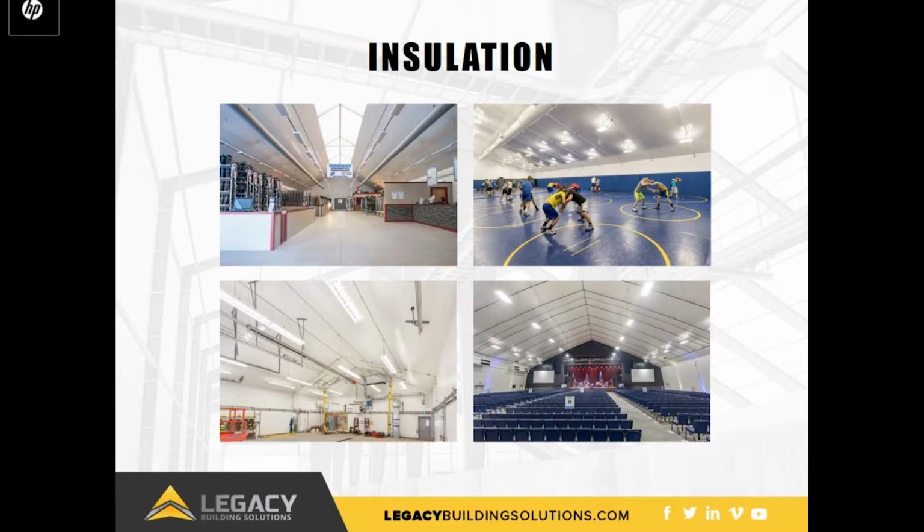Insulated fabric buildings have two big advantages over similar metal buildings. The first is that the fabric liner makes a tight vapor barrier for the building, reducing heating and cooling costs through reduced air leakage. This is a result of a continuous membrane liner, instead of the fabric vapor barrier in a typical metal building, which is dependent on tape joints to maintain continuity. The liner also provides a clean finish inside the building, effectively hiding all exposed framework. This can lead to better acoustics within the building as sound is not bounced off multiple surfaces. This has proven to be beneficial in sports centers and entertainment venues.